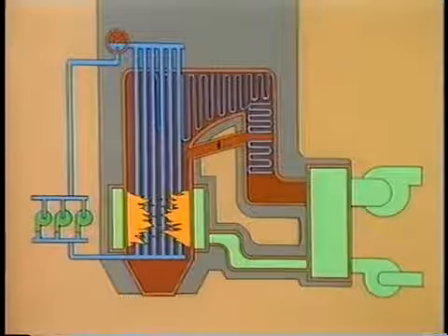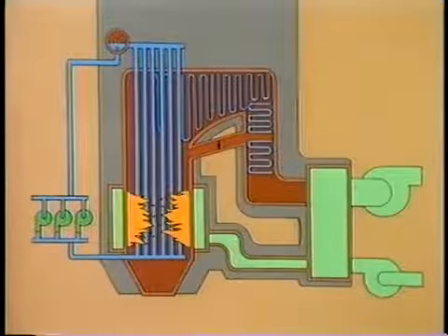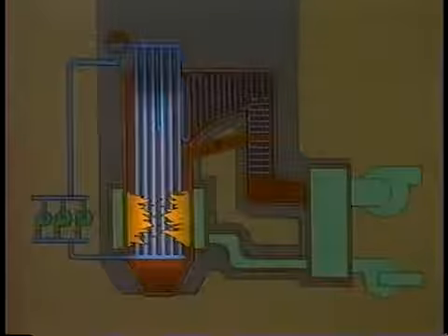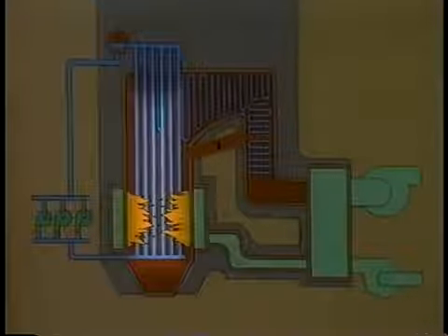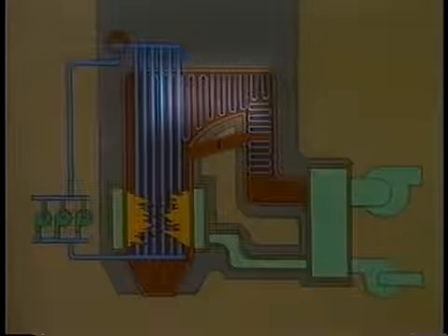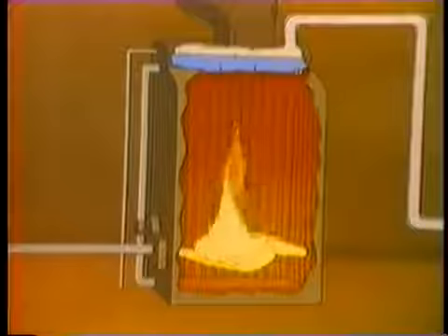Depending on the location of the rupture, it may endanger the boiler flame. Ruptures in the furnace area of the boiler are usually the most critical. Ruptures in the area of the secondary superheater may also cause a flameout, while a rupture in the area of the primary superheater and economizer will not usually upset the boiler flame. When a boiler tube ruptures, water or steam is released into the boiler under high pressure. If the rupture occurs in the furnace area, it may extinguish the boiler flame.